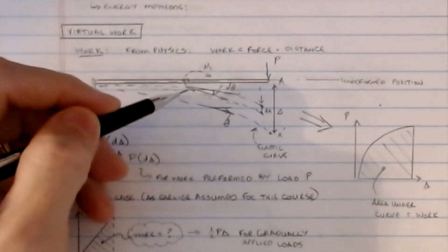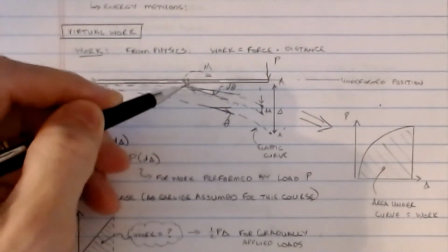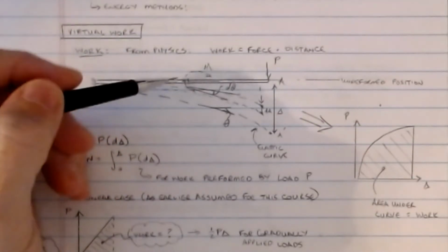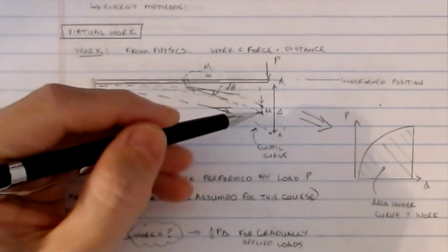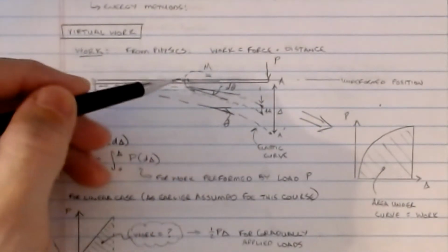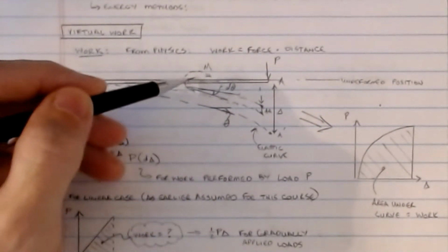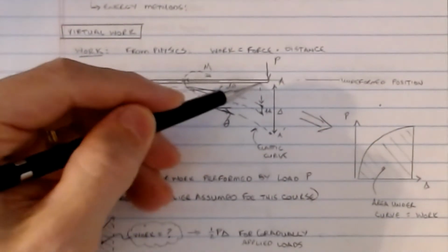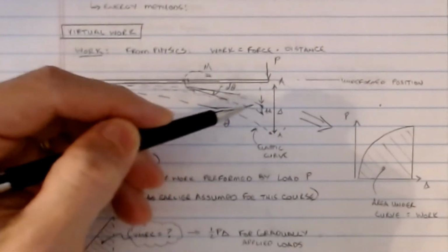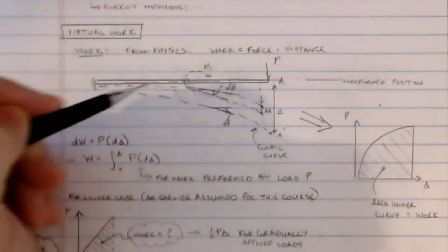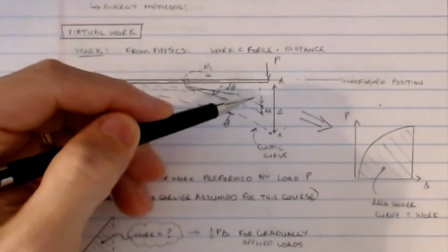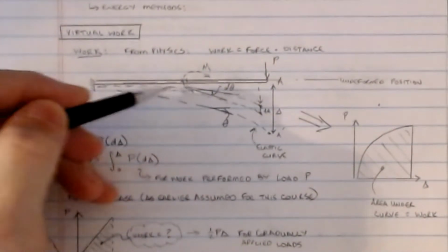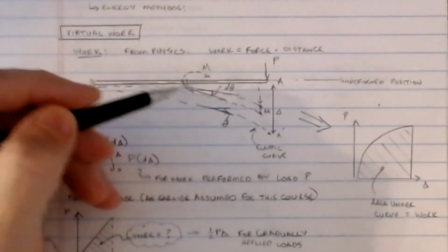Then that can translate, if I look at the left end and the right end, like what we did when we set up our tangential deviation derivations in the moment area method, to account for some portion of the total deflection that is caused by the rotation of that element right there. Then the next one causes a little bit more, and the one after that causes a little bit more. It's the sum of all of those little incremental displacements, due to the behavior of each individual little element, that add up to the total. And that's the basics for what we're going to look at.